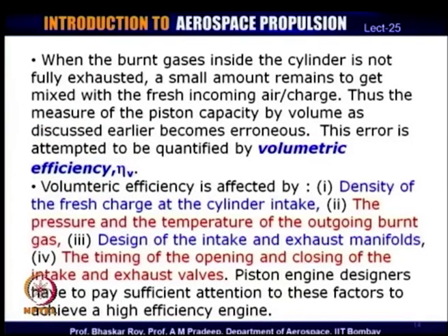Now, when the cylinder is operational, we have just seen that at the end of the exhaust stroke, the burned gases are exhausted from the cylinder. However, we also know that at the end of the stroke, when the piston reaches the top dead center, there is a certain amount of volume which is still containing the burned gases.